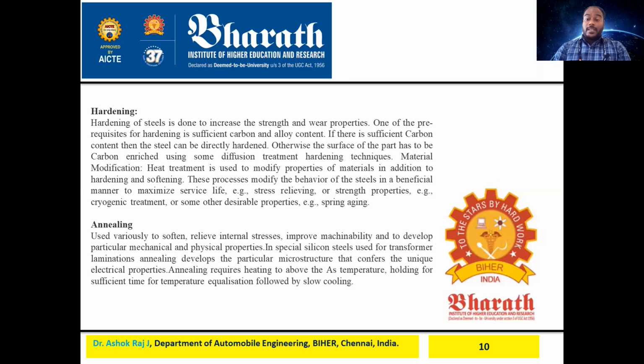And in the special silicon steels used for transformer lamination, annealing develops a particular microstructure that confers unique electrical property, and this is used for electrical applications also. Annealing requires heating to above a certain temperature, holding for sufficient time for temperature equalization, followed by slow cooling.